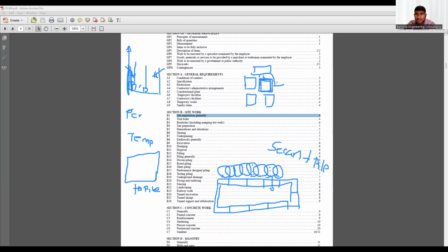Also, if the soil pressure is huge, they cannot control it with temporary shoring. If the water flow is huge along with the soil, it will push the temporary shoring, so they will also go for permanent shoring. Permanent shoring has two types. One is secant pile, which they mostly use. Another one is a diaphragm wall, which is the expensive one. They decide based on constructability and the pressure on the soil.